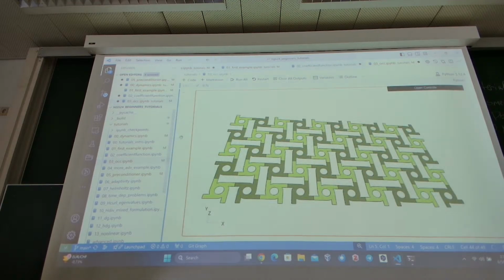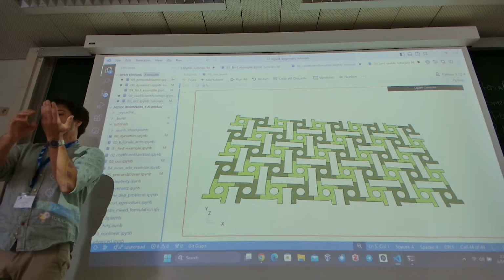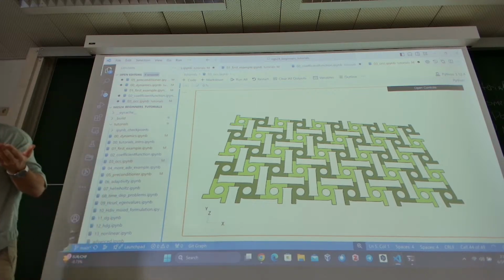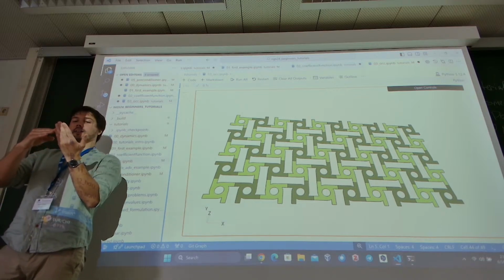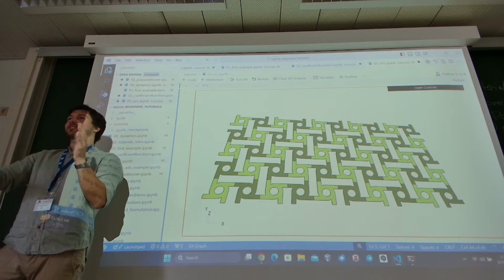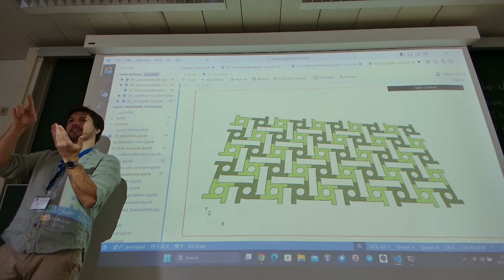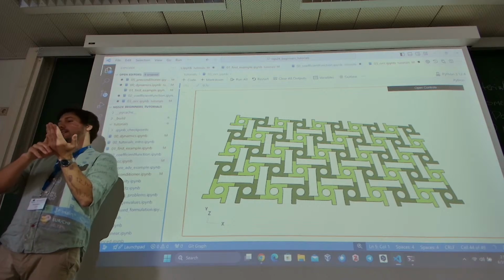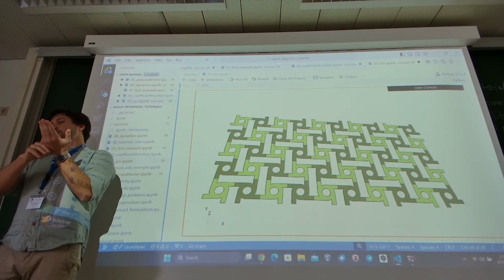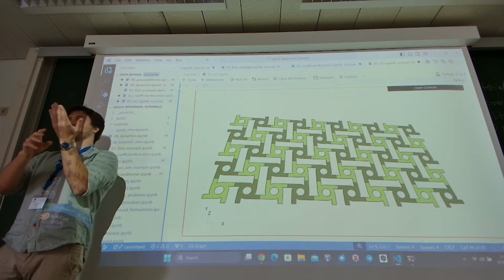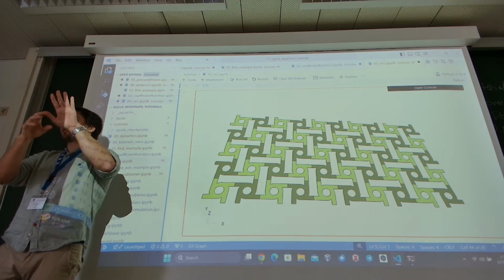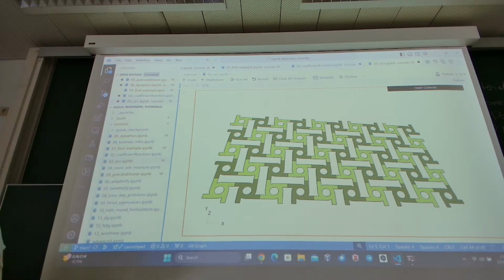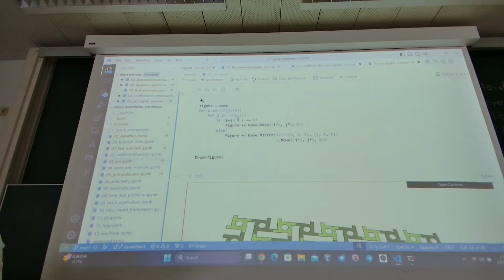In this case, what I did was to take this cell and then create a grid that is, I think, 6 or 7 times 4. This can be considered as a matrix, and if the index i plus j is an odd number, you do nothing, and if it's an even number, you basically mirror it. So i plus j divided by 2 equal to 0, otherwise mirror.